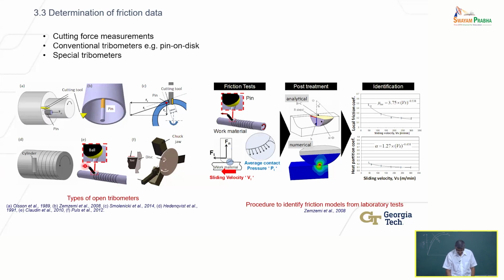So people have been working on finding testing methods. The simple tribological tests you might find in the design handbook, the value of the coefficient of friction between two materials, that you might use for mechanical design, are no longer adequate for this. So you need testing methods that describe frictional conditions representative of what happens between the chip and the tool.